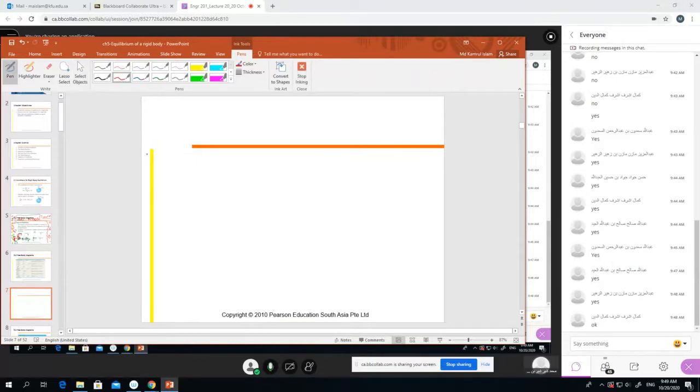I'm repeating three times because this is very important. Roller support, right? It is usually shown like this in freehand. Roller, right? And it will give you only vertical reaction. There is no horizontal reaction.